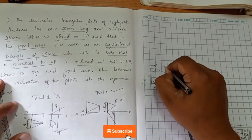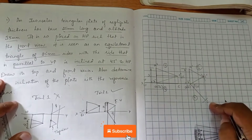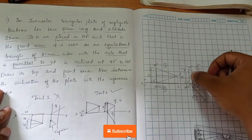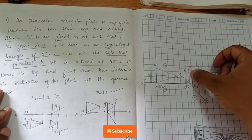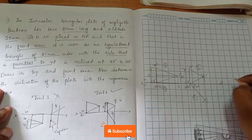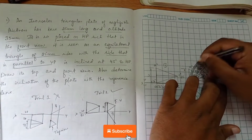You can see how this problem proceeds: 1, 2, 3 and 4. First we have drawn this, second, third and fourth. Now the fifth. You can see in this question, the side that is parallel to VP is inclined at 45 degrees. This is A dash, B dash, which is parallel to the VP. Now we have to incline this end by an angle of 45 degrees. How do we do that? Here we mark the point B dash, and at this point I'll take an angle of 45 degrees.